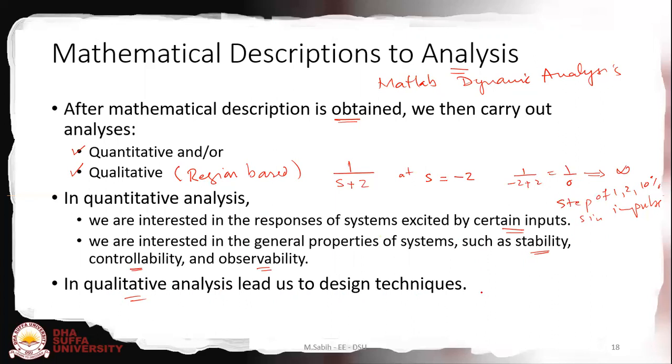So what will be the value of, let's say, k? Let me expand the same thing. If I have 1 upon s plus k minus 2, then I will ask what values of k will result in a stable system. You might come up with a range of values.